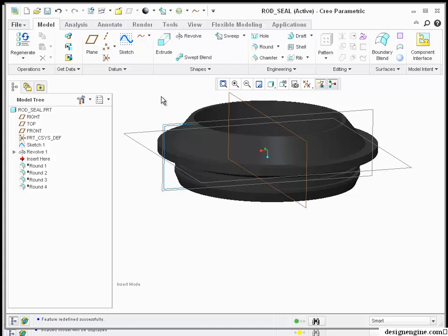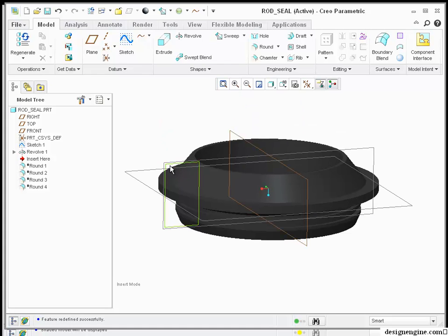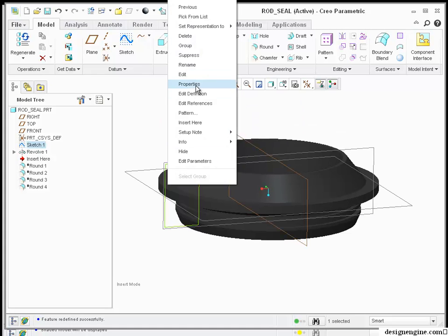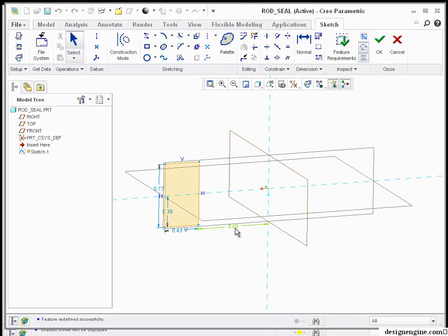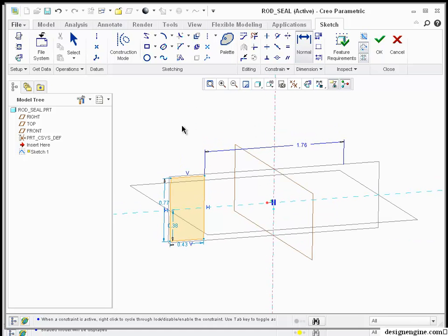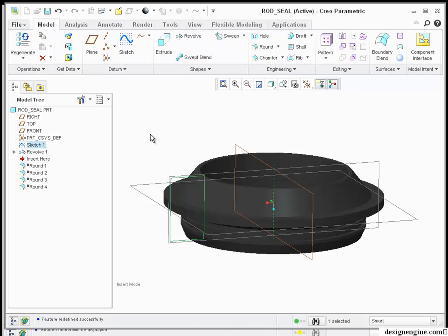Now that I've done that, in Creo, I'm going to go back and redefine this and set this to a diameter dimension. So let's go ahead and put my center line in and dimension that appropriately. Left click, left click, left click, middle click. Now it's a diameter. That's because a center line does what it does best. It forces symmetry.